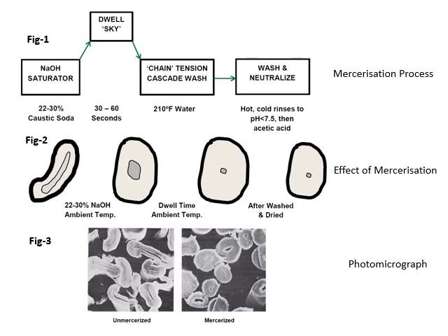Figure 3 shows actual microscopic photographs of unmercerized and mercerized fibers. Unmercerized fibers, as you see, have a very long lumen and collapsed walls. But in the case of the mercerized fiber, the cross section shows a very small lumen and a circular cross section of the cotton fiber.